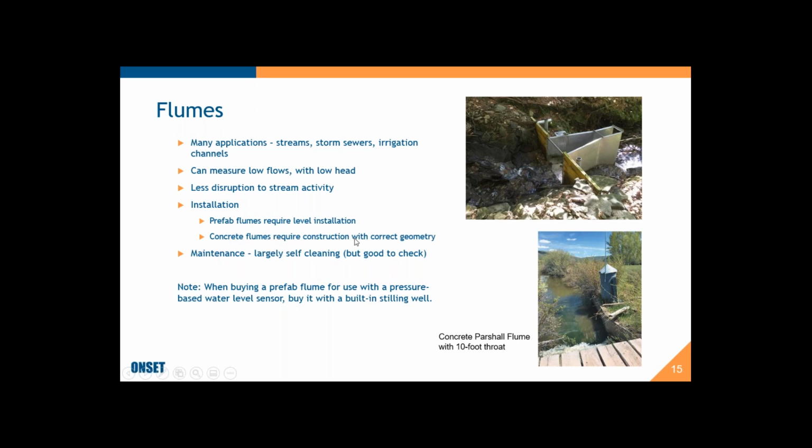Concrete flumes can also be constructed, but you got to be very careful with the geometry to make sure that it's meeting the required geometry so you can get accurate measurements. Another advantage of flumes is that for most flumes, they're more self-cleaning, just because there's constantly water flowing through them and there's no hard obstruction. They keep themselves clean better. Some types of flumes, like a ramp flume, you got to be a little more careful about keeping them clean because they can collect sediment.